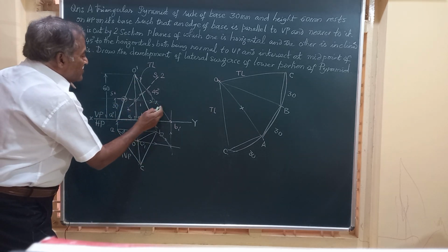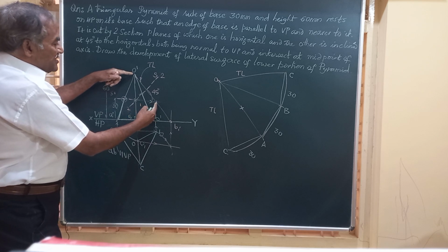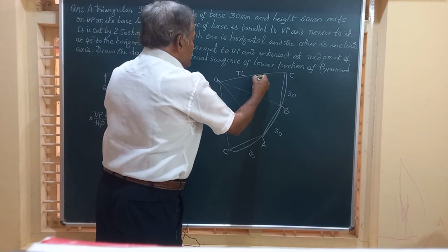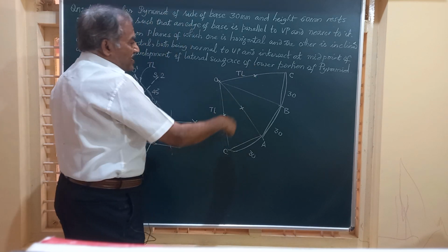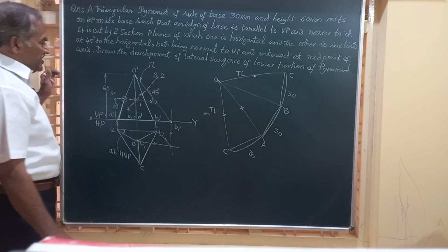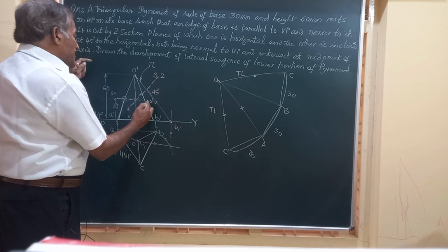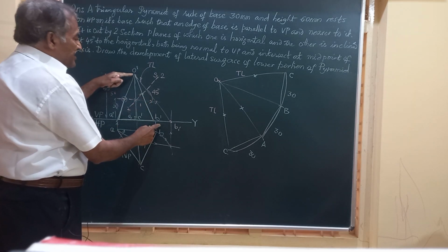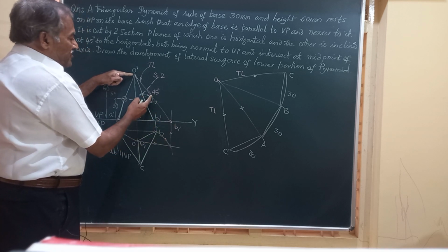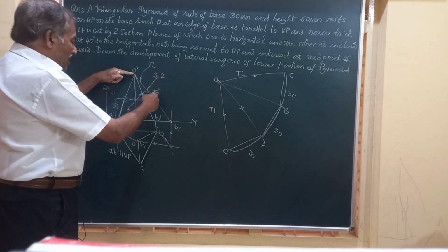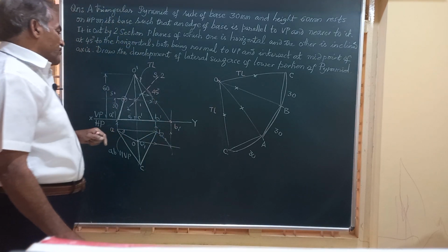So I have to transfer that to the true length, mark the same measurement on OC, the second slant edge, and also here you have to mark OC because there are two times OC drawn. And then friend, OB is cut here. OB is also, O dash B dash is not the true length. Hence, we have to transfer that to the last line, O dash B1 dash. Take that measurement on OB, the slant edge OB. Say we are getting here. So we got 4 points, friend.